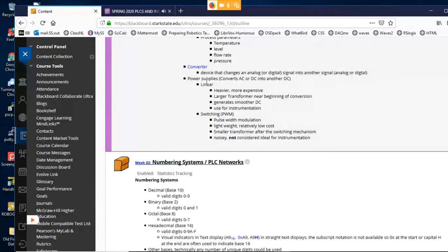We also talked about power supplies. We have linear power supplies or switching power supplies. And last week, when we talked about the load cells, I talked about filtering and stuff. I think the problem with our CompactLogix PLCs is that they're so noisy with those load cells because they actually have a switching power supply attached to them instead of a linear power supply.